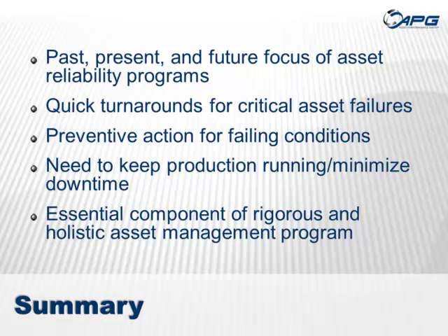Does or should root cause failure analysis stop at the physical causes, or do we need to continue the process until we find the systemic causes? Yeah, right on. Great questions. What we've talked about primarily in this webinar is getting to the physical cause, or basically where is the malfunction on the equipment. But ultimately, as one of my colleagues said, it always boils down to biology or physics, which is the root. So it's either a human or some sort of environmental issue.